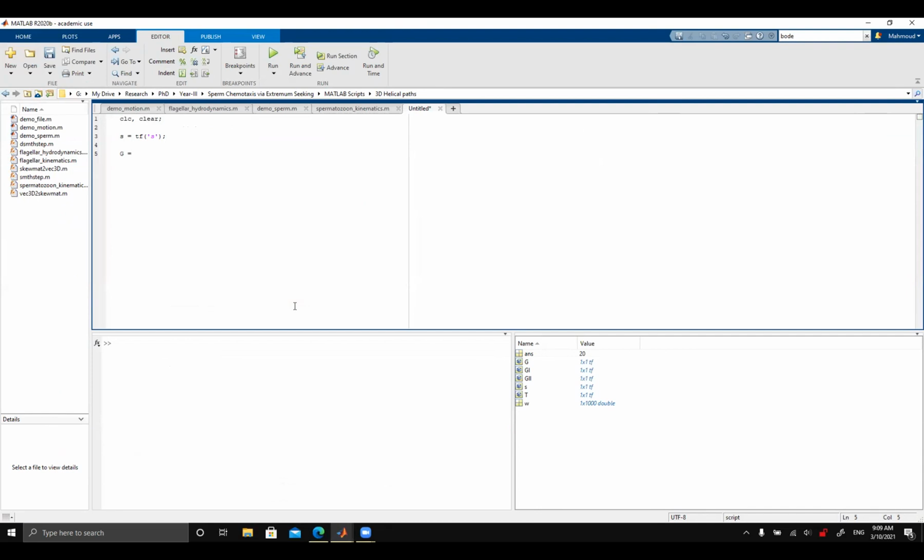So the original transfer function was 5 divided by 2 times s plus 5. And then we added the steady state error, right? So now we have G is going to be equal to 100 divided by s times G. And we designed a lead compensator. Let's call it lead. And that was 1 plus 6 times 0.026 times s divided by 1 plus 0.026 times s.